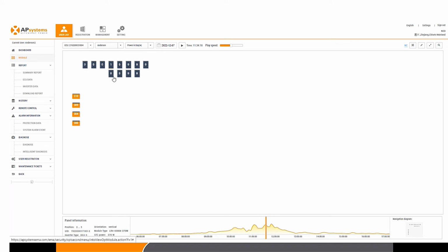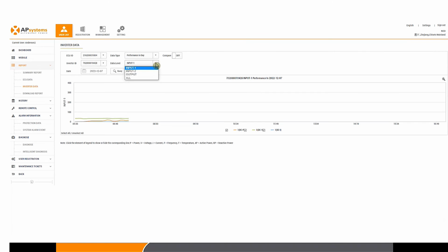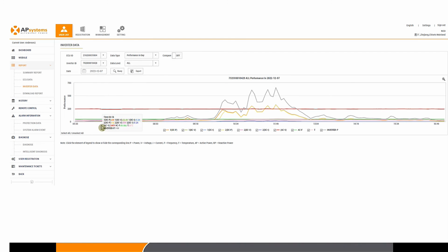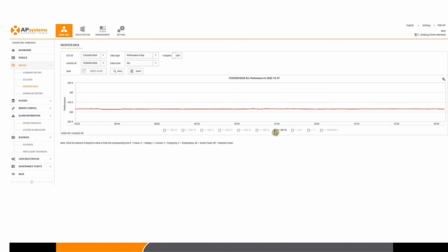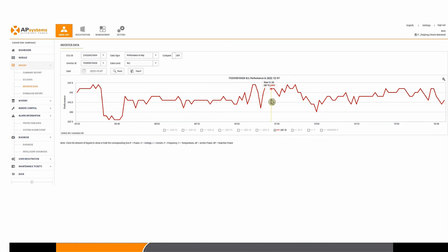And you can kind of even guess that because those panels are working, it means that the issue is somewhere between the junction box to the first microinverter on the roof, on the northern panels. Because if something were wrong between the junction box to the inverter, to the switchboard, then these panels will not even switch on anyway. Because if you look at the data on the western panels, the AC voltage is normal. It's normal enough anyway. So it's 240, 250, whatever.